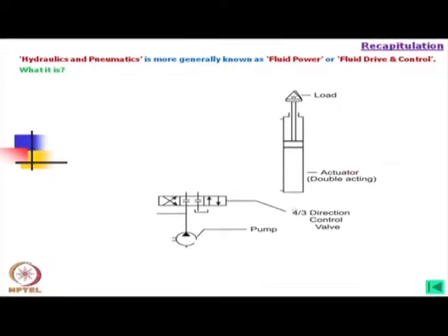Now, we can directly connect this pump output to this. So, this will pump the oil inside and it will go up, but the question is that the next moment we have to bring down the piston for the next assignment. In that case, definitely we have to allow this oil to go some other path; we cannot return this oil through this pump. So, now we will think of some arrangement by which we can do that.